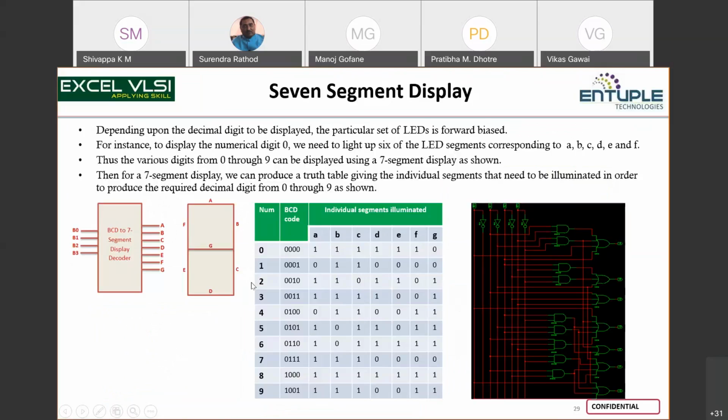Here you are just writing the code, especially for converter circuits, with no clocks and no reset. It is just these inputs, and then you just represent the outputs. It's also an encoding technique: you are encoding a particular number to a value in order to display the number in a certain way. So it is all your if-else statements, or the case statement, and assign statements, whatever Verilog you use.